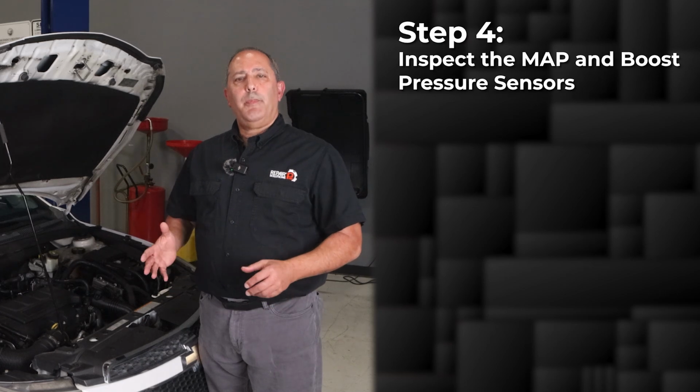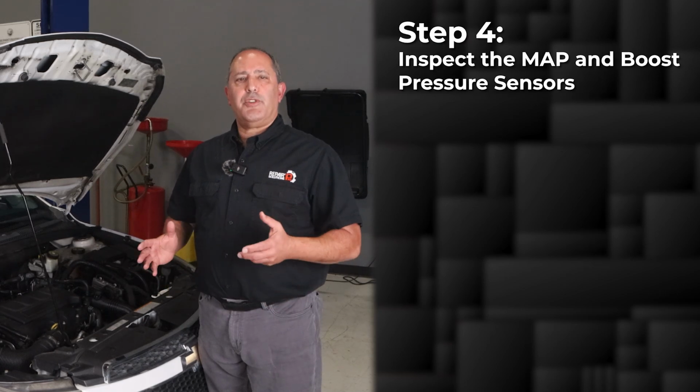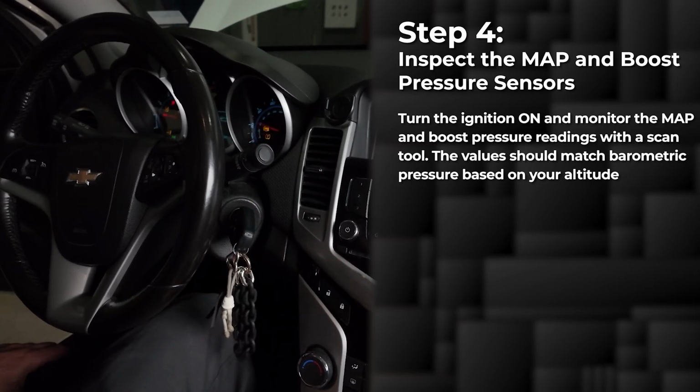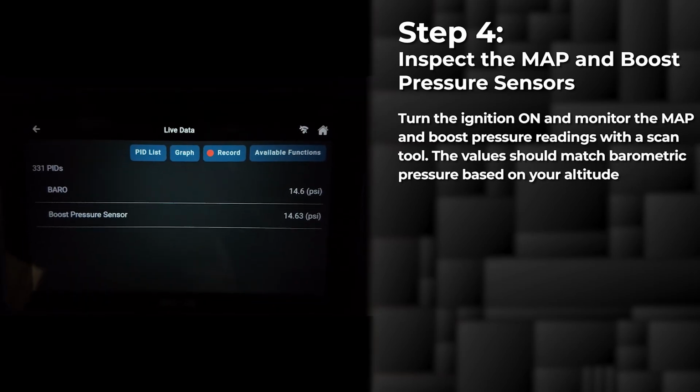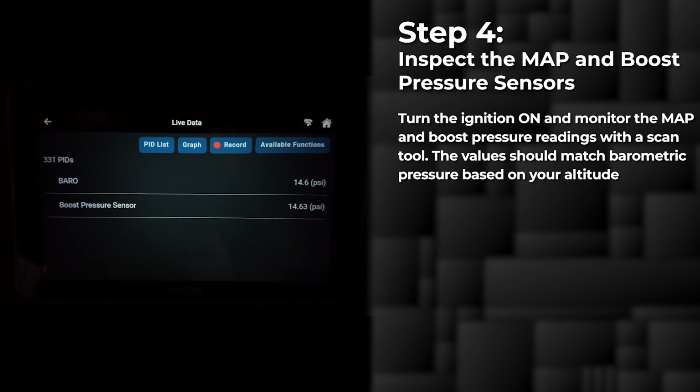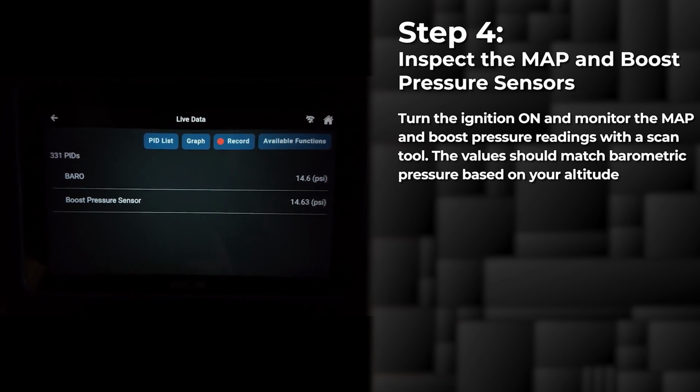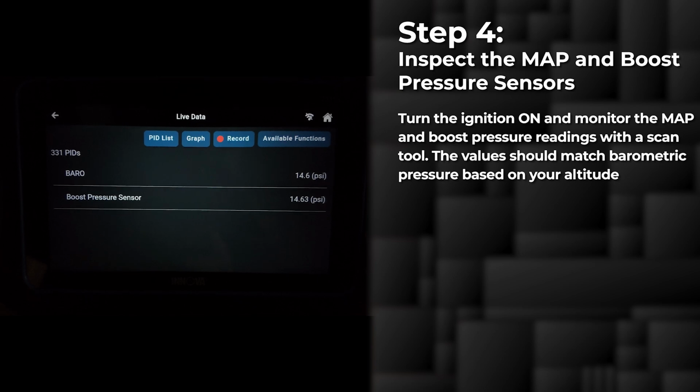Step 4 is to inspect the MAP sensor and the boost pressure sensor. Turn the ignition on and monitor the MAP sensor and the boost pressure sensor values using the scan tool. If the values do not match, replace the MAP sensor or the boost pressure sensor and then perform the repair validation.